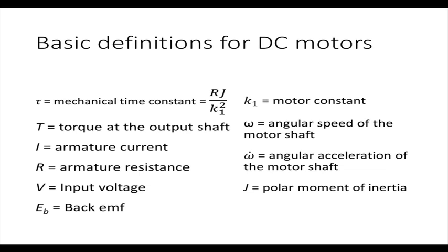given a command to move the table at, say, 50 millimeters per minute. In that case, if you are moving at 50 millimeters per minute, then it is expected that the motor should be speeding up and attaining this particular speed right from t equal to 0, from the first moment itself.